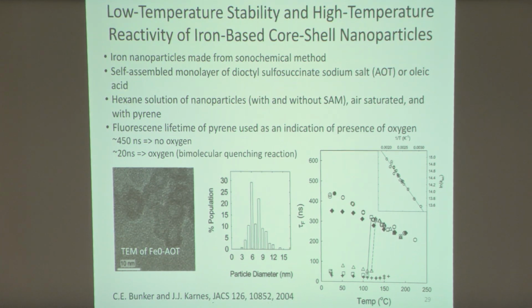If the newer turbine engines are going to be running under conditions where the fuel, before it gets injected, goes supercritical, it gets pretty hot. What they've found is that if there's any oxygen absorbed in the fuel, it starts to oxidize and lead to coking reactions, so right at the injector they have problems. So the idea was to take nano iron particles and coat them, and just before that temperature occurred, the ligand would come off, and the iron would preferentially react with the oxygen to create iron oxide, preventing the coking reactions that lead to carbon deposits on the surface of the fuel lines.